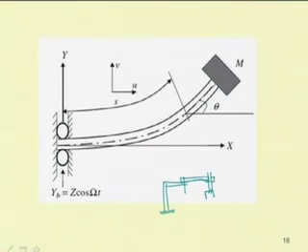In this case, this is a joint with a prismatic link. So, it can move up and down. The base is rotating. So, you have a revolute joint here, another revolute joint here and you have a prismatic joint, and finally, the end effector has a rolling motion. So, this is a SCARA robot. In this case, you have a joint with prismatic motion.